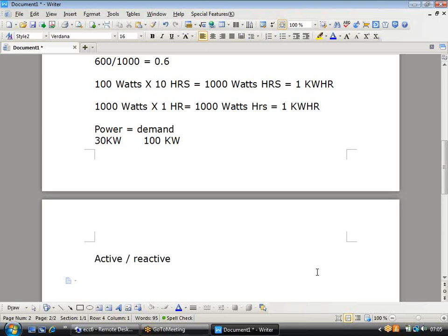What is power factor? It's some kind of a relative proportion between active energy and reactive energy, okay. Total active energy divided by total energy will give some kind of power factor, okay. So if the power factor is less, it's going to be a loss for the department, okay. Whereas more or less in household applications, power factor is 0.9 and more, okay. In case the power factor is less, you can also increase the power factor by adding some power factor correctors in the grid line, okay.